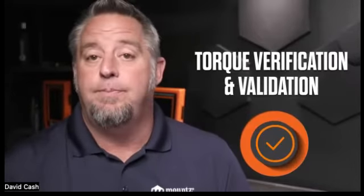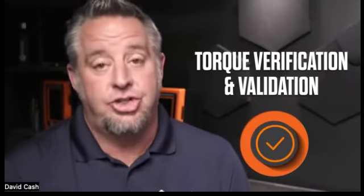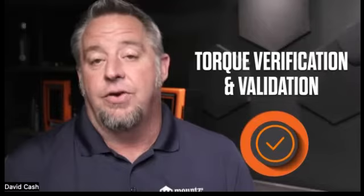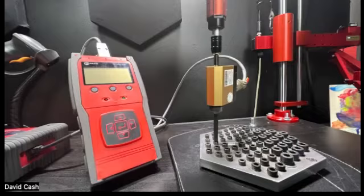And this can be done based on a weekly requirement, a monthly requirement, could be a shift requirement, but whatever frequency may work best for you. But this can be done again with the use of a portable analyzer with a rotary style sensor. And so this type of sensor goes in between your tool and your application, and it allows you to be able to measure the tool actually in use on your part. And so this gives you a real good representation of what is happening actually on your part.